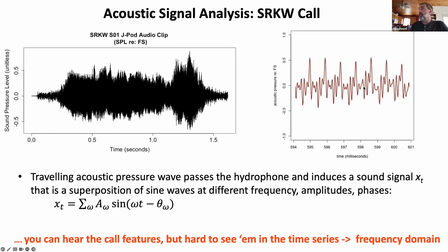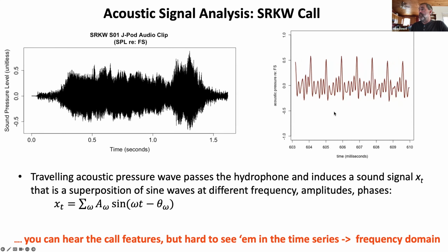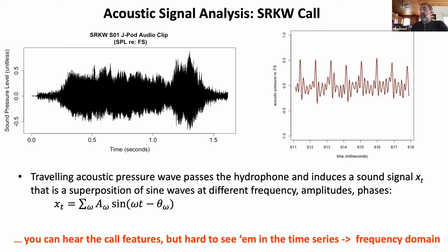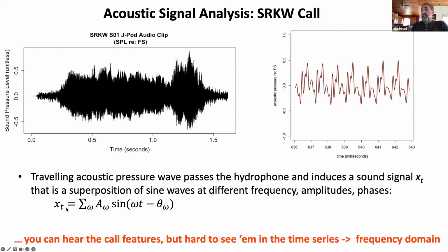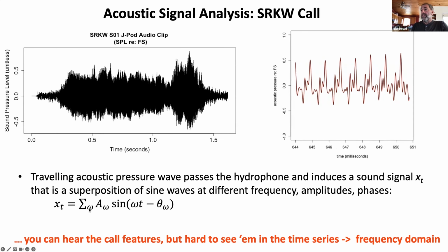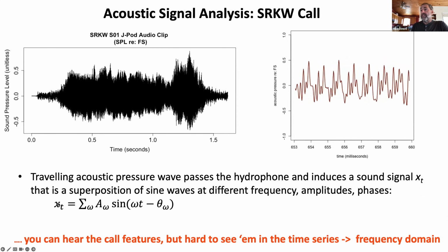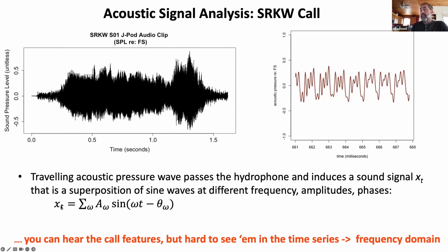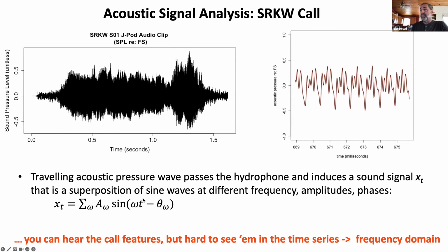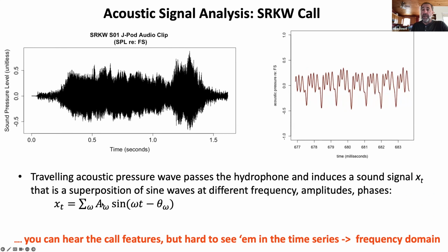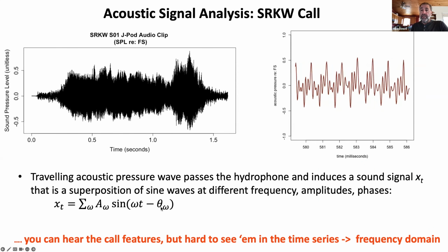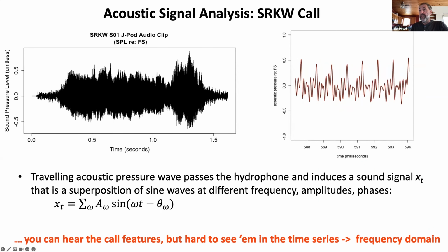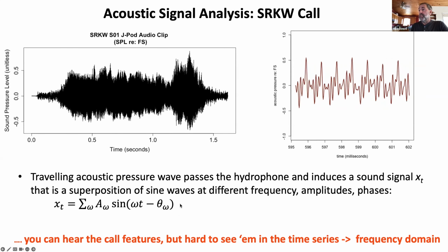If you look at my little movie here, you can see that the sound pressure signal is made up of essentially sums of sinusoids like that. It's just periodic signals added together. And in a sense, you can model and analyze sound using this. This is the received sound pressure level. It's basically a sum of a bunch of different sinusoids at different amplitudes, frequencies, and phases. So it's relatively straightforward to analyze, and this is a pretty good description of the sound.